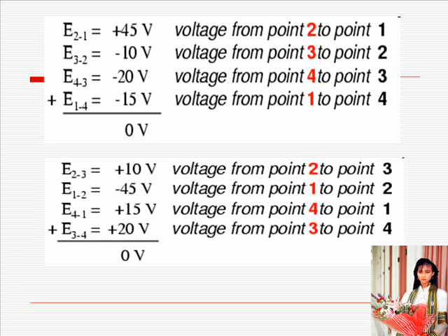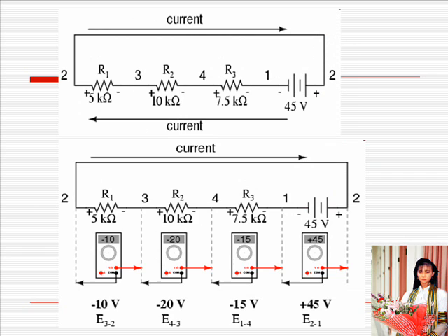To demonstrate, we can tally up the voltages in loop 3, 2, 1, 4, 3 of the same circuit. This may make more sense if we redraw our example series circuit, so that all components are represented in a straight line. It's still the same series circuit, just with the components arranged in a different form.